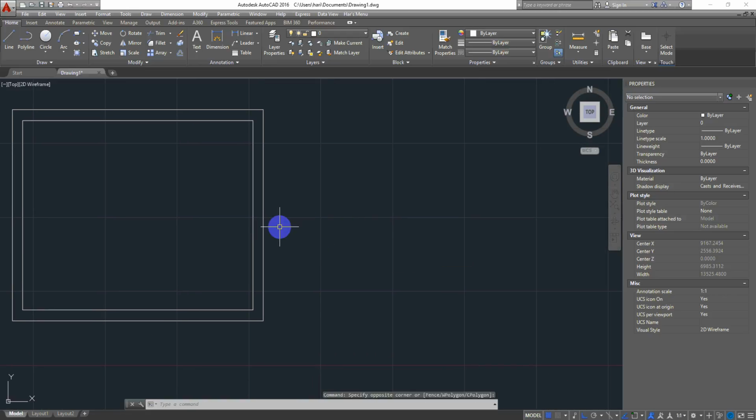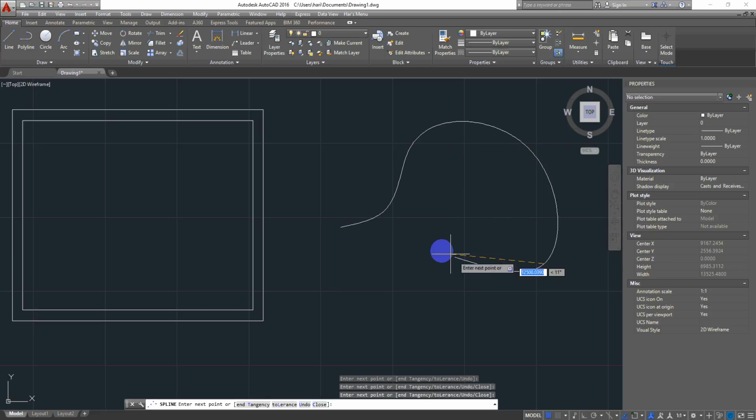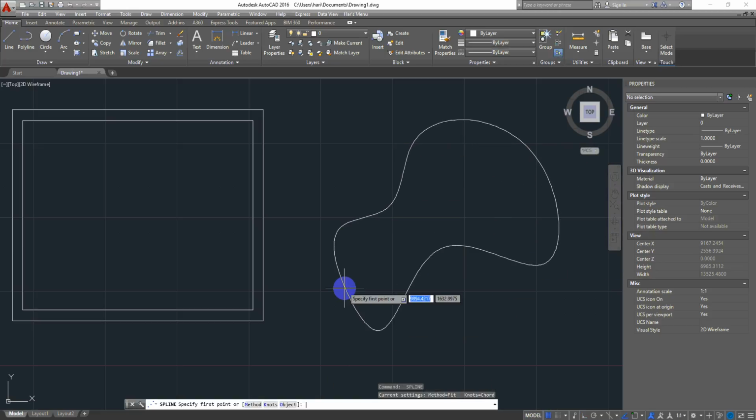Usually what happens is like in AutoCAD, if you want to have the length and width of a room as a text, I know so many experts use AutoLisp for these things, but you can easily use dynamic block for this purpose, provided the room is a rectangular room. If you have some rooms like this, some organic shape or something, then it doesn't work.